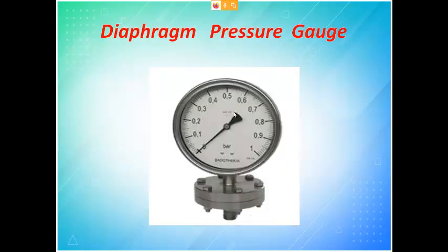So this is the instrument which you might have seen. The pressure is always in terms of bar. Here you will have an inlet. The air stored in that particular tank will go through this valve, and this will enter the pressure chamber of the diaphragm. Okay, here is the diaphragm, the elongating material which I have told about. Then comes your mechanical part, and this needle will show the reading.